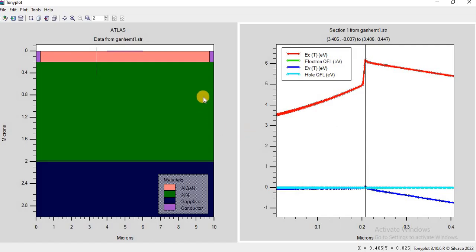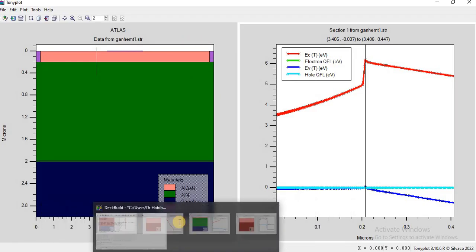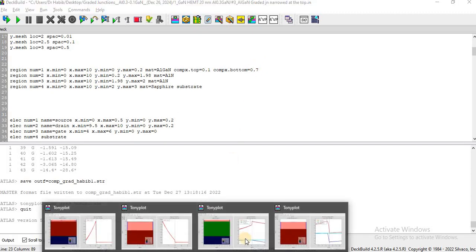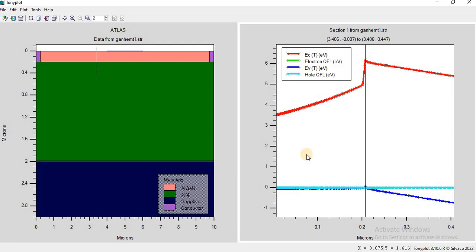And then if we do both the aluminum nitride film and the aluminum gallium nitride film, then we will have higher carrier concentration at the top, and then we can make really good contacts to the entire structure. And then if you reverse the order of these, then the band gap order of the heterojunction also reverses. So that is pretty much it for today's video. We covered compositional grading and ternary alloys. Now you can use these techniques to optimize your own designs, and you can also include other kinds of materials as well in Silvaco TCAD.